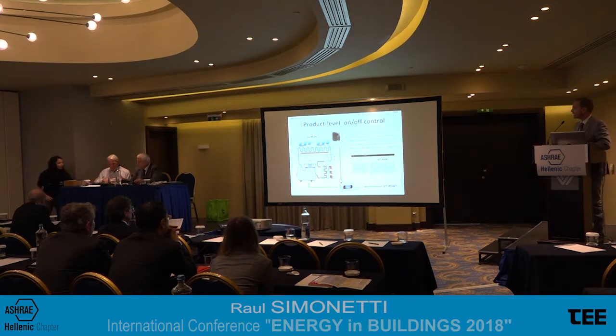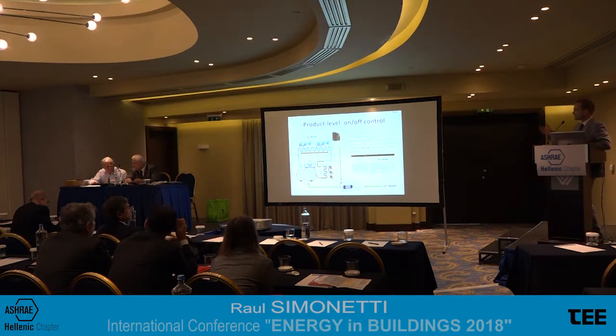This is a typical outcome of the eco-design requirements, but also of other programs that you may have in the USA or China or also Australia. With a particular focus on a refrigeration cycle, you have a compressor, you have a controller that drives the compressor through an inverter, number 7 at the bottom, in order to modulate its cooling output according to the load, which is sensed by the sensor.